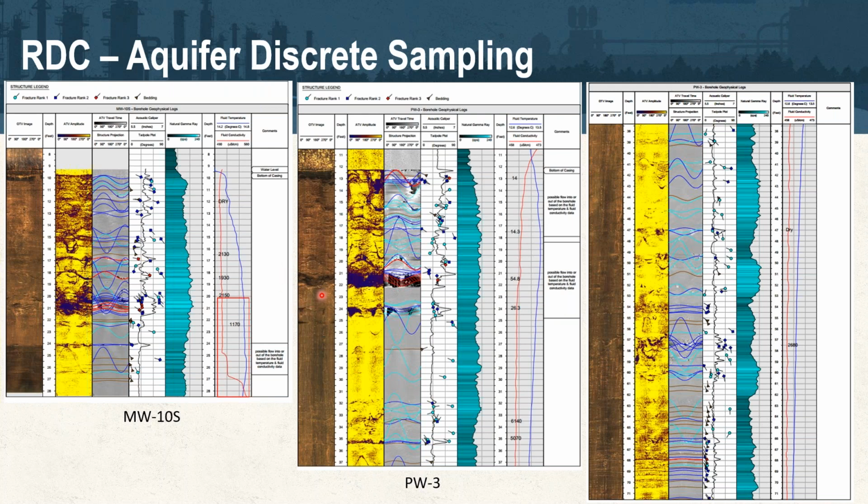Looking at the pointer on the screen here at roughly the 21 to 22 foot interval, a significant high K zone was identified from the geophysics as a potentially likely candidate for contaminant mass moving across the site. A previous remediation effort was to inject potassium permanganate, upgradient from this well, and utilize extraction from this well to pull the permanganate through this high K zone to this particular location.